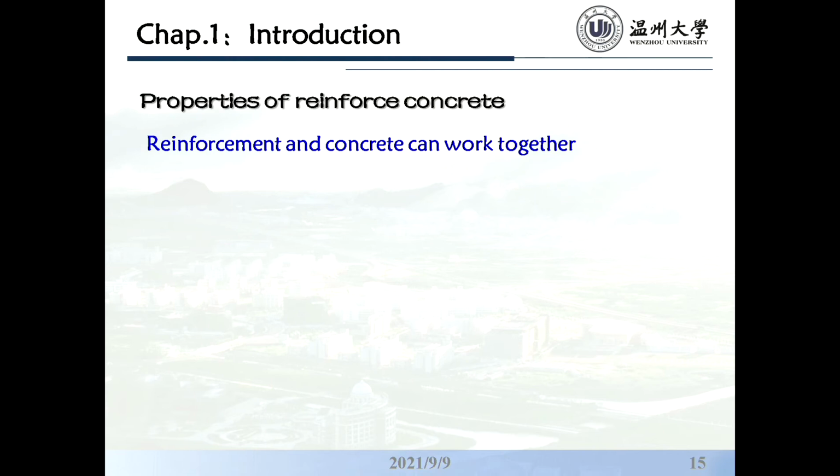And then we calculate and get the internal forces in the structure. Two important ones are the moment and the shear force, and we also need to care about the force on the boundary. In the preliminary design stage we get these things, and then we use this load and force to do the structure design and anything else.